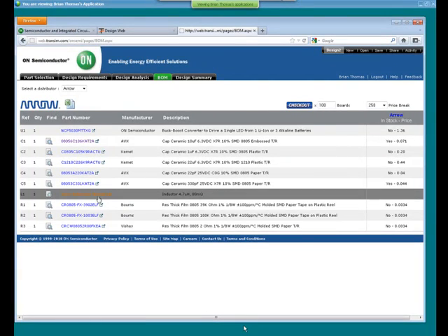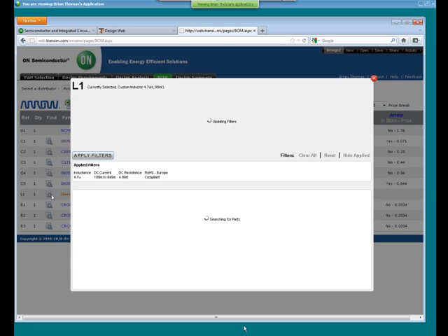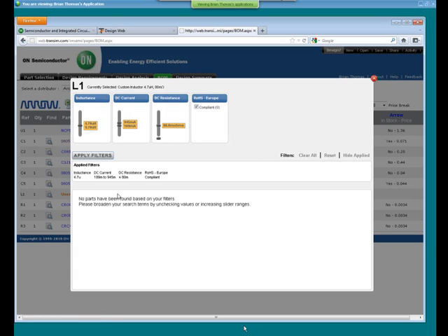And the reason it's saying user selection required is it's not finding something that specifically meets those requirements. And so it's looking for a 4.7 microhenry, 189. And I'm pretty sure that that one is probably either limited by the DC resistance or the DC current. And so what I'm going to do is give myself a little bit broader window for DC current.